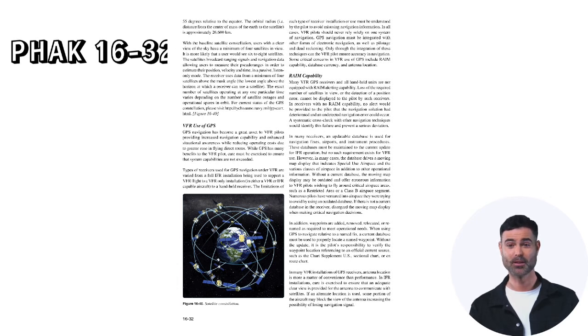In addition, waypoints are added, removed, relocated, or renamed as required to meet operational needs. When using GPS to navigate relative to a named fix, a current database must be used to properly locate a named waypoint. Without the update, it is the pilot's responsibility to verify the waypoint location referencing to an official current source, such as the Chart Supplement US, sectional chart, or en route chart.